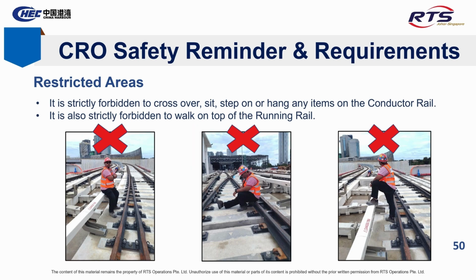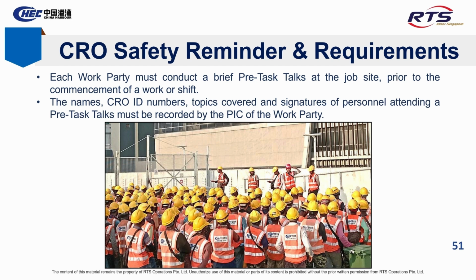Slide 50, Restricted Areas. Never step, sit, cross over, or hang anything on the conductor rail. Do not walk on top of the running rail. It's strictly prohibited. Slide 51, Pre-task talk requirement. Before starting any work or shift, each work party must conduct a pre-task talk.